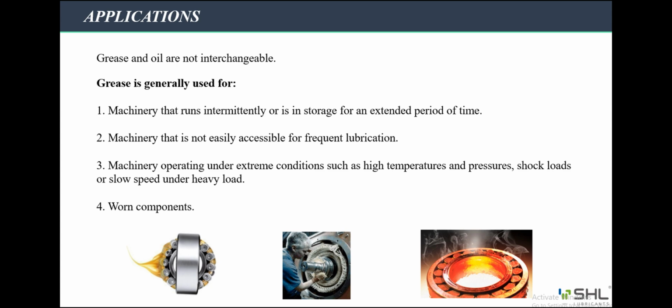3. Machinery operating under extreme conditions such as high temperatures and pressures, shock loads or slow speed under heavy load. 4. Worn components. Grease maintains thicker films in clearances enlarged by wear and can extend the life of worn parts that were previously lubricated by oil.